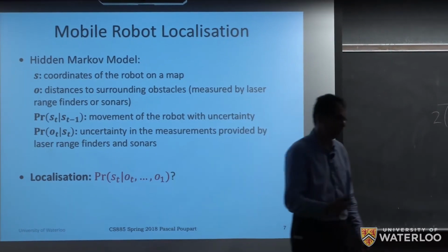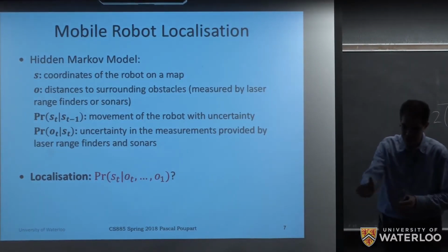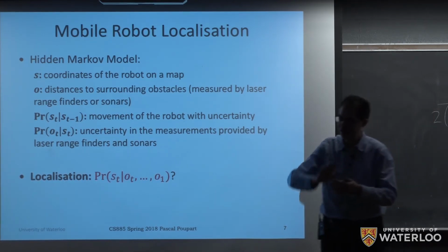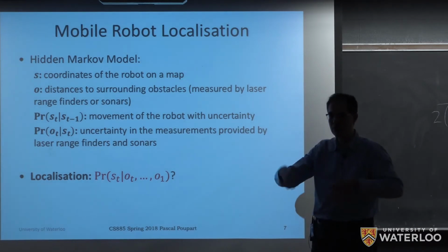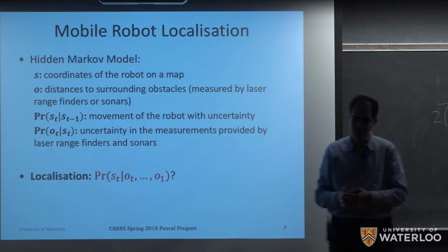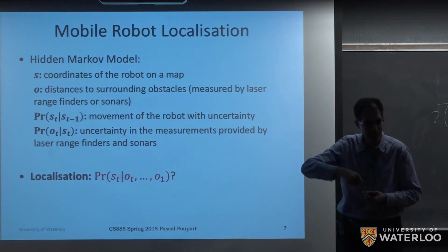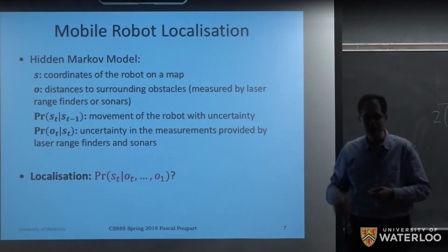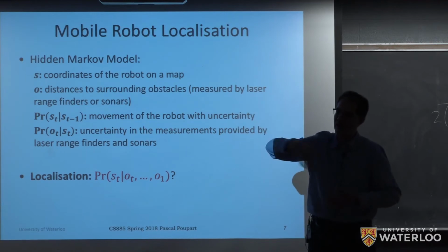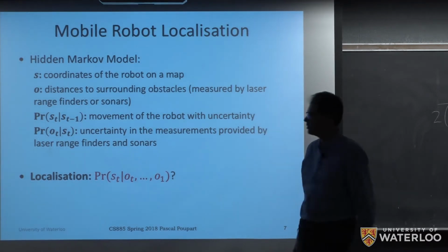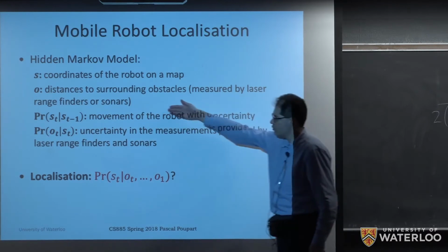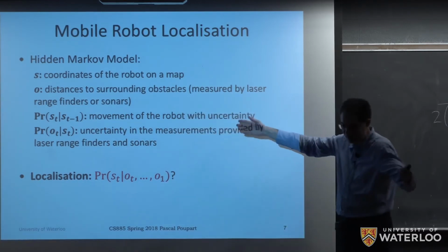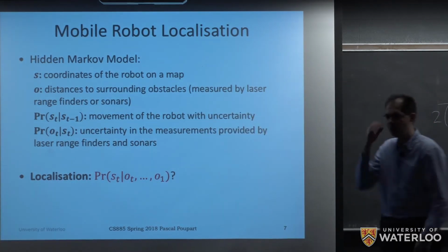The classic problem is if you shoot a beam on a mirror or a piece of glass or some surface that does not have any texture, it might get reflected in a way where it will think that there's no obstacle, because it doesn't get reflected back to the robot, but it gets reflected into a different direction. As a result, it thinks that there's no obstacle there, or the obstacle is much further. And if you consider sonars, sonars are in fact extremely noisy. So in general, any sensor will have some type of noise, and you need to take that into account.